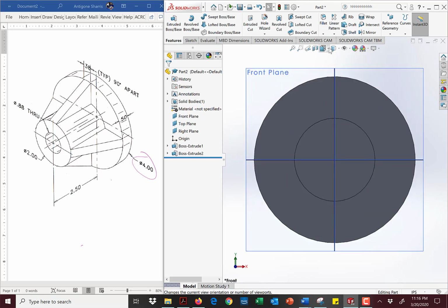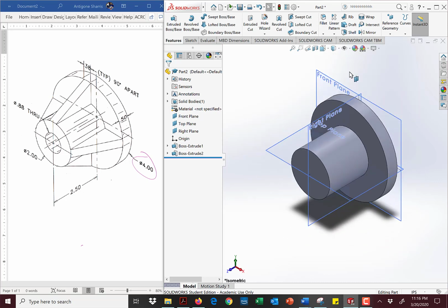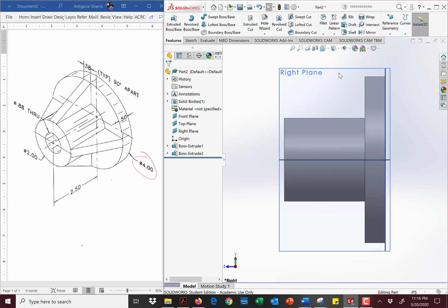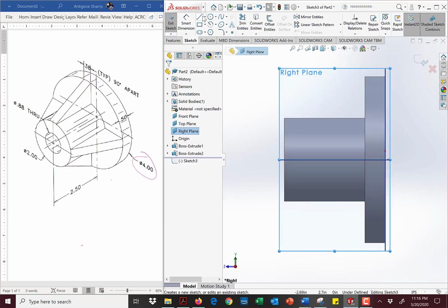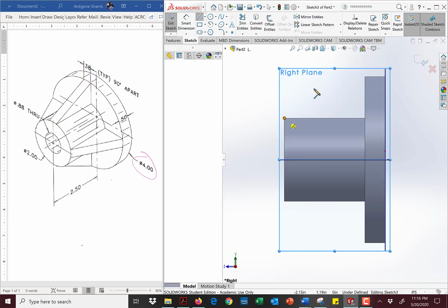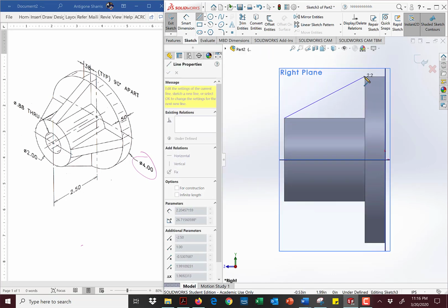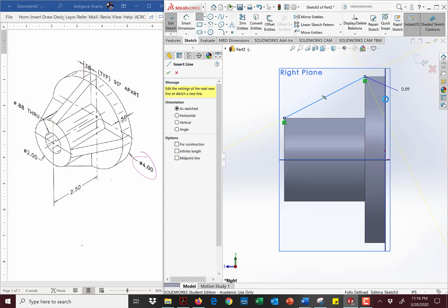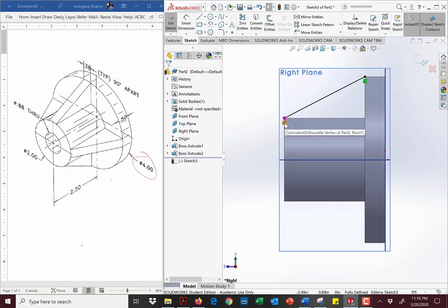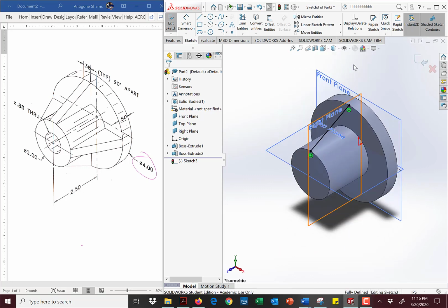Here's my basic geometry, yep, see that? Go back to isometric, go back to actually my side view. Let me go to the right side view. Okay, there it is. I'm going to pick this plane, I'm going to create a sketch, and I'm going to go ahead and create the resemblance of a rib. This is kind of what I want it to look like. I'm going to attach my 2 little points. There you go. It's hooked to the front face. It's hooked to that back face right there. So everything looks hunky-dory, peachy keen, and fuzzy-wuzzy. There. Put them all in together at one time.